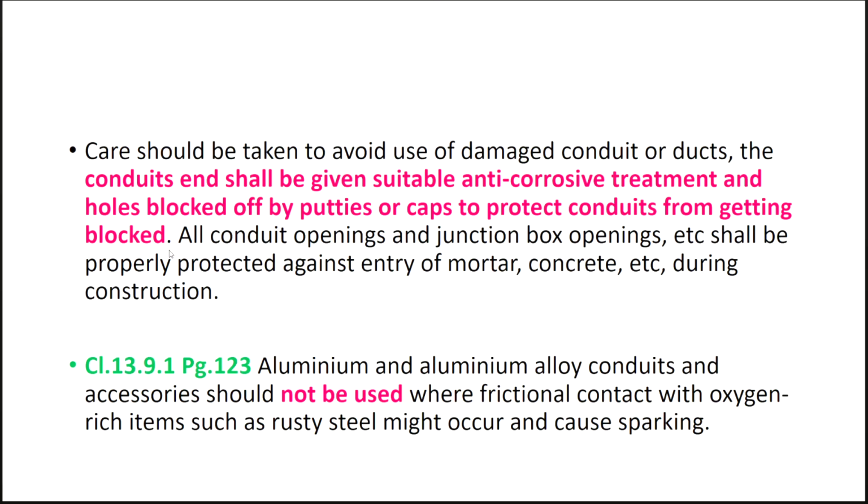Now many times what happens during execution, the coupling is taken off or worn out, because labor works and a lot of activities are there. Once it comes off, your concrete might go inside the conduit. So all conduit openings and junction box openings etc. shall be properly protected against entry of mortar or concrete during construction.